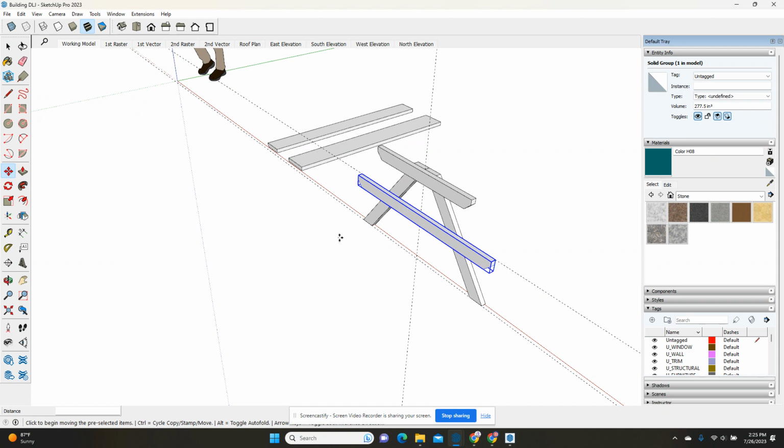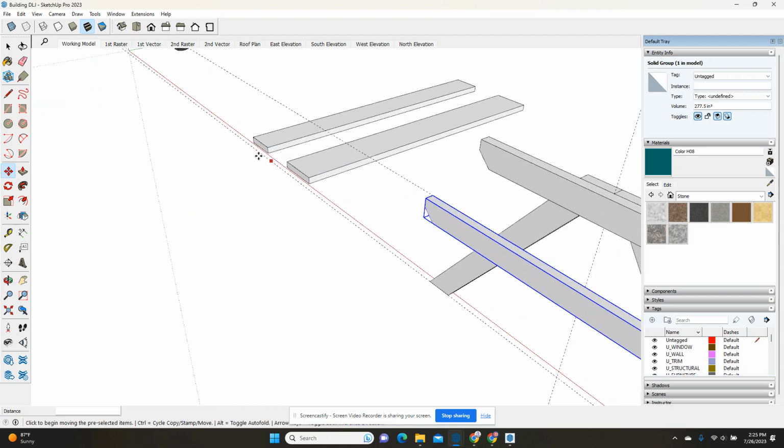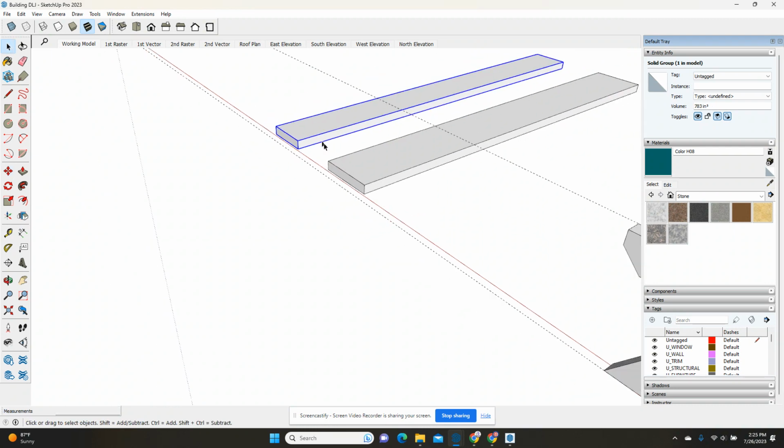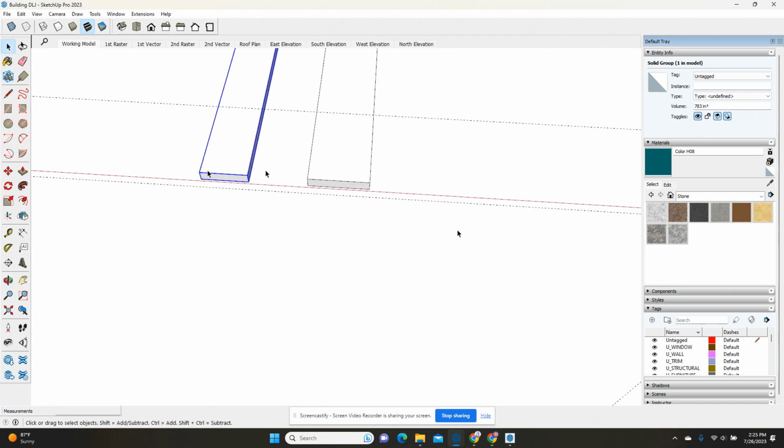Now, we're going to add one seat board to one side, and we're going to add one tabletop board to the middle. The rest of the boards we'll place later so that it still allows us to have some access to see underneath the table. So I'll start by coming over here, going to my selection arrow, and selecting my top board, which is the narrower of the two. It's only 7.5 wide.